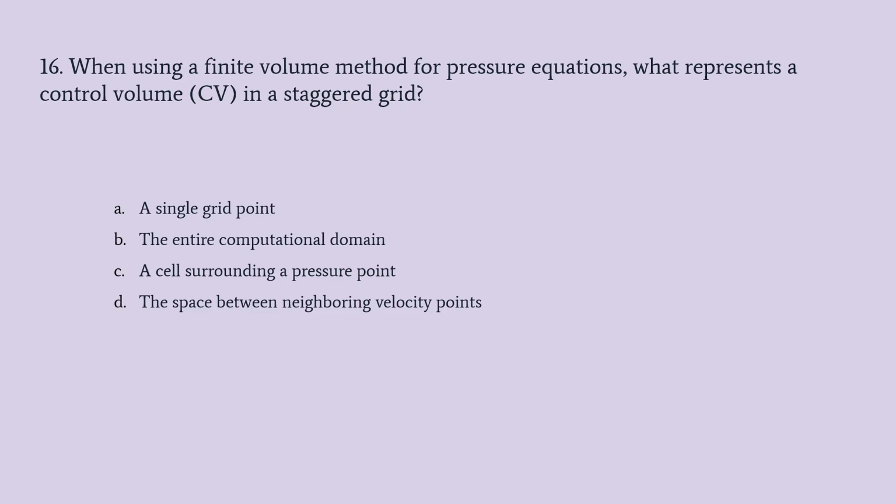I have drawn two different meshes earlier for staggered grid arrangement. If we want to draw it in a single structure, without drawing a lot of different lines, I have to represent the position of pressure as well as velocities in a single mesh. Then how will I do it? The center point will be represented with the pressure, and faces will be velocities. With the help of that, try to solve that question.